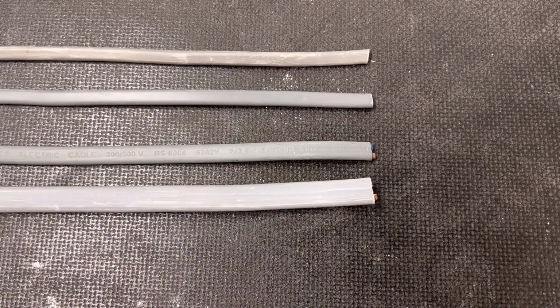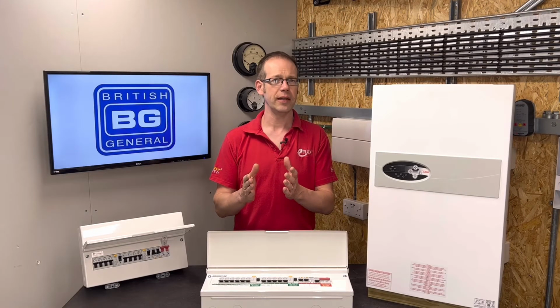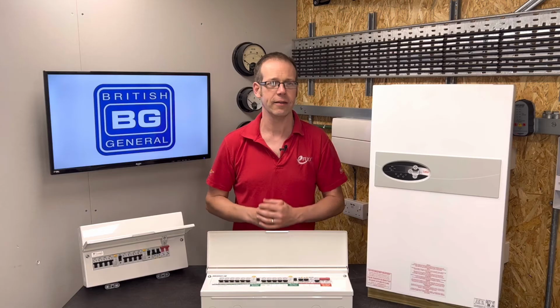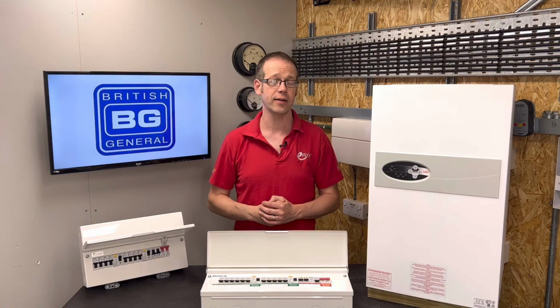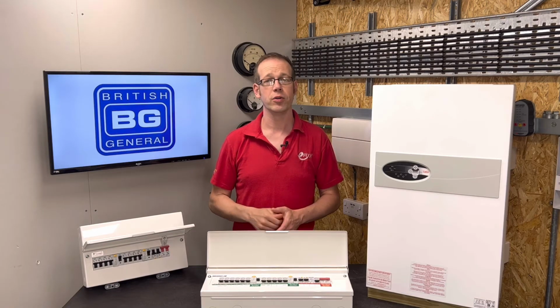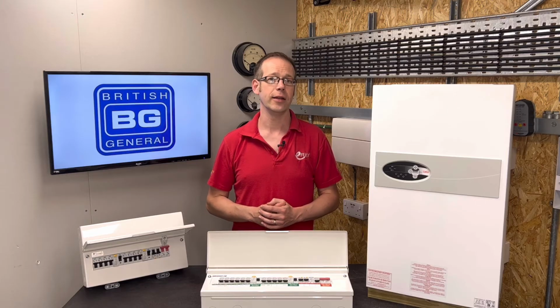Interestingly, these values are pretty close to each other, meaning that we'd want to make sure that none of our rating factors change during installation. For example, if we were to run a third cable in the group of conductors, we might find that it derates the cable to the point where we'd need to upgrade it to a larger size. It really emphasises the importance of good circuit design and sticking to that design during the on-site installation work.